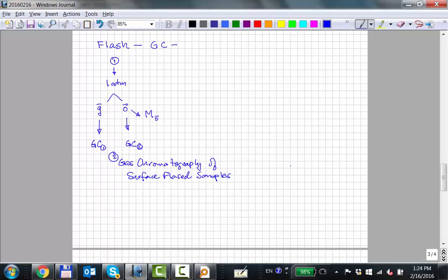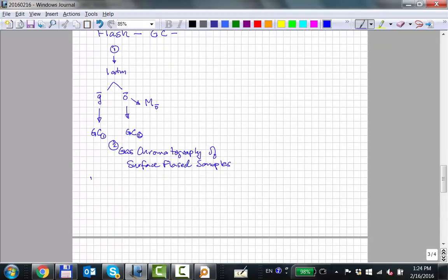we have to recombine the methane in the flash gas together with the methane in the flashed oil to find out how much total methane you have, right? So we have to recombine this flash gas and the flashed oil to find out how much methane total was in the sample